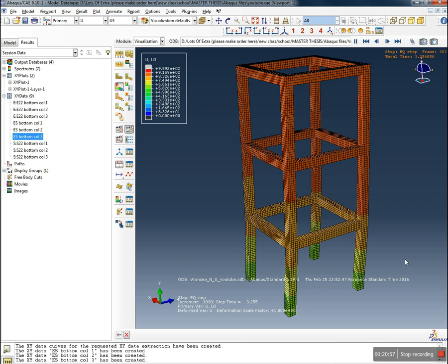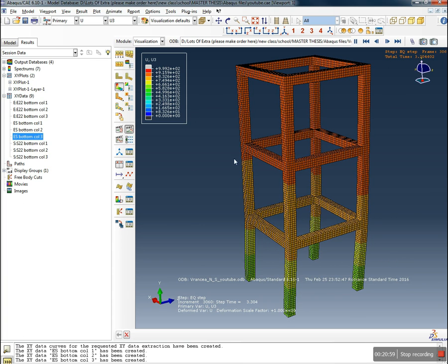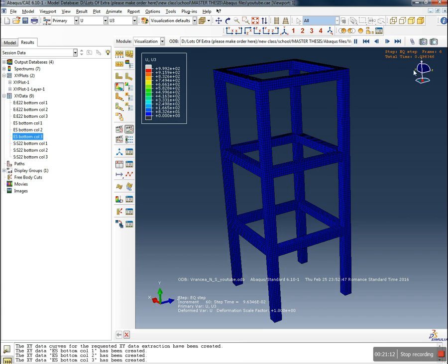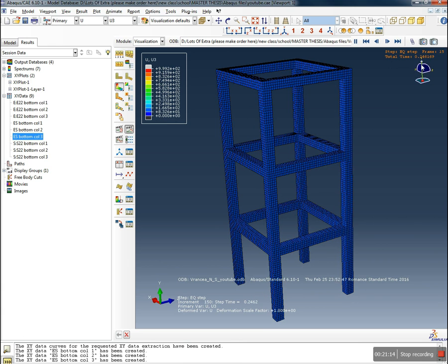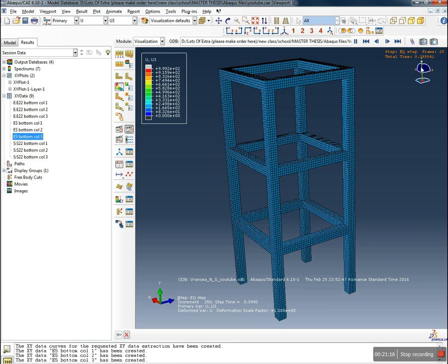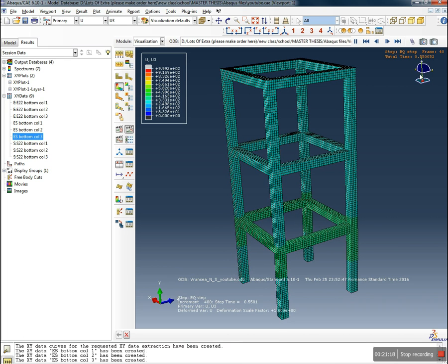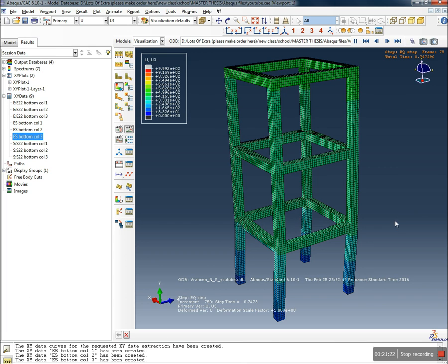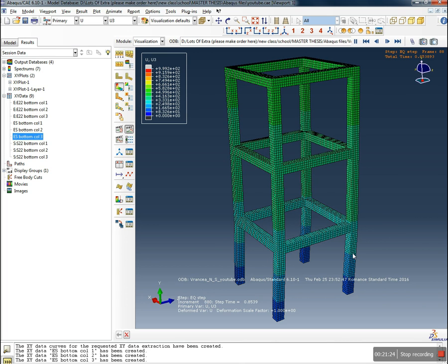But anyway, this is the displacement field. If you want to say, we had a stress field in our first animation, and the second animation shows our displacement field on the z-axis, because if you want to go on x, you see u1. If you want to go on y, you have to check for u2, and on z is u3. Yes, and now you can see it's already starting going smoother.